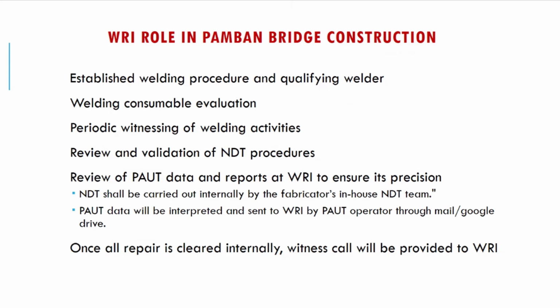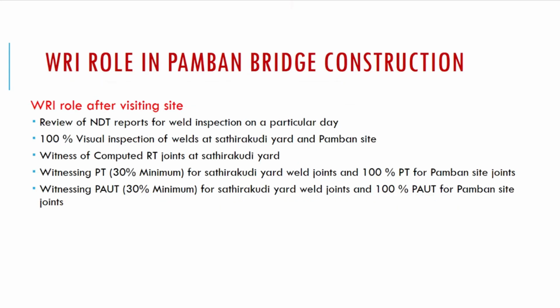of welding activities, review and validation of NDT procedures, and review of PAUT data and reports at WRI to ensure its precision. The NDT shall be carried out internally by the fabricator's in-house NDT team. PAUT data will be interpreted and sent to WRI by that fabricator's PAUT operator through mail or Google Drive. Once all repairs are cleared internally, the witness call will be provided to WRI.